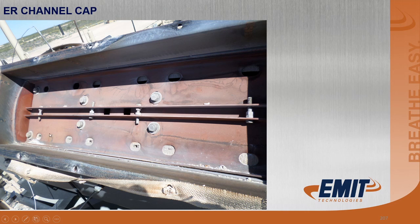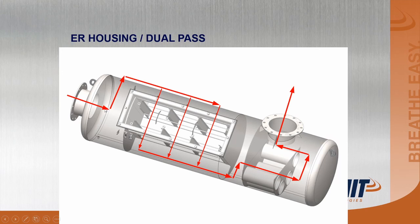Tight regulations. ER housings, anything typically greater than 500 horsepower in a rich burn application, we would choose to put on the ER housing, just so that you always have the option to get those numbers very low. And here's the flow path. Goes through the top and down through each set of elements, through the silencer and out.